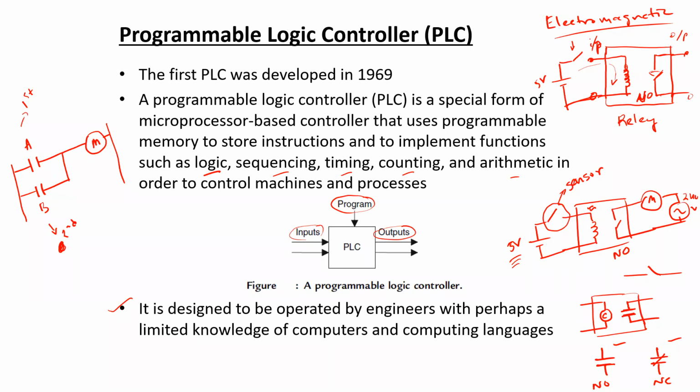Yes, so simply we are implementing an OR logic, because if any one of the relays is active, or the relays are getting energized, their corresponding contact will close, and there will be a path of current flow for the motor. So in this way, using physical, electromechanical relays, the control systems can implement different logic functions or other sequencing or timing operations, because there are some relays, timing relays or counting relays, that can provide time delays as well.